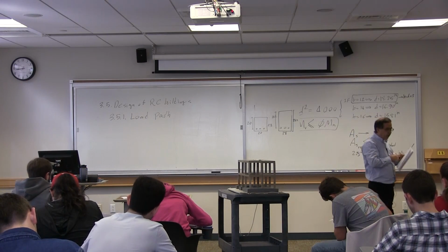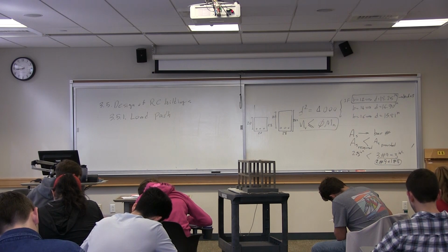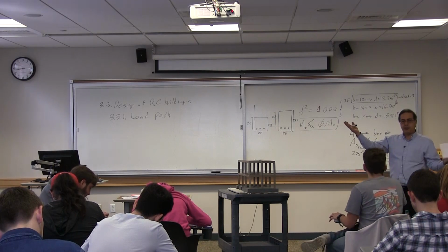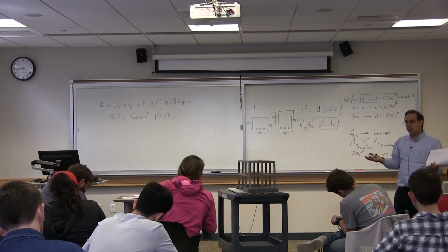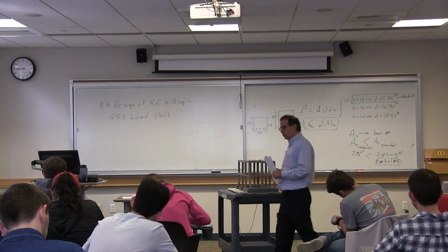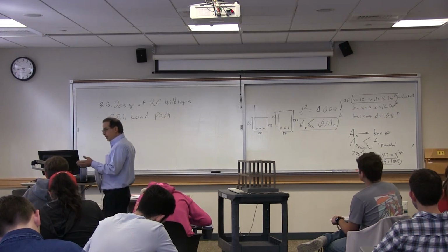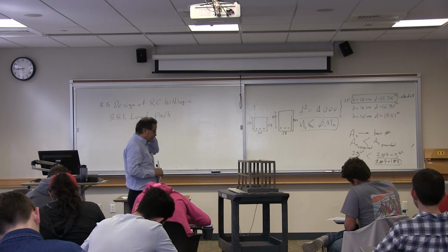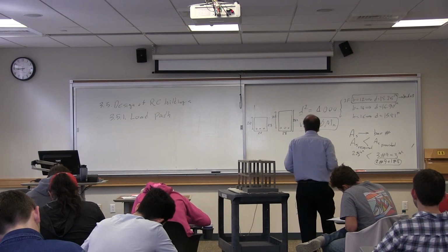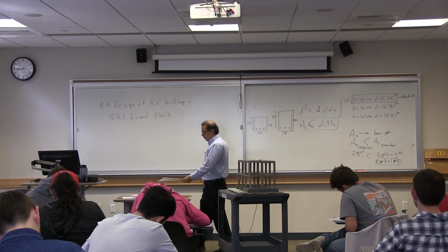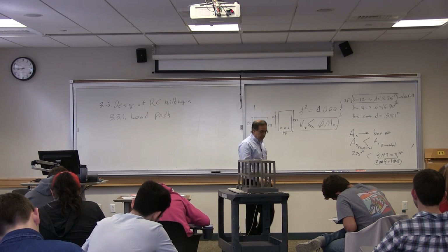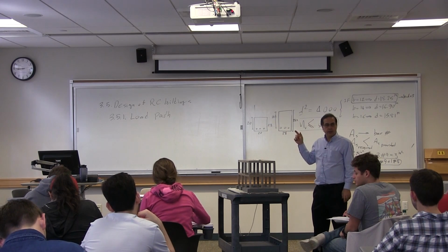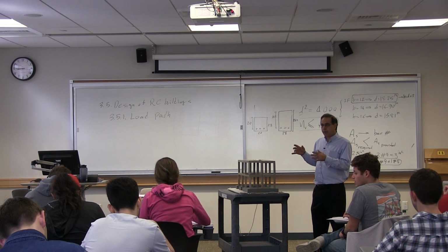As you recall, I defined structural engineering as a profession in which we transfer loads from point A to point B. That's our technical job. How to transfer loads from one point to the other, usually from the point of application to the support. When you are transferring the load from the point of application to the support, you need to make sure there is a complete load path and understand the load path.